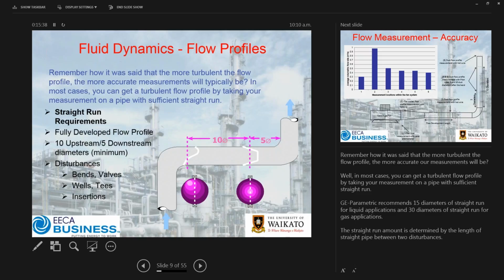So you want 2/3 upstream, 2/3 downstream. As you can see, around elbows and valves or other actuators in the duct, or flow dampers if you like, you'll get a disturbance in the flow. And you look at the peak velocity distribution, as you see there, of the two cross sections. We obviously need to be very careful with the point on the left there. You can end up getting it horribly wrong. You might get lucky and get it roughly right, but the potential error is significant. So you do need to think very carefully about where you're going to take your measurements.